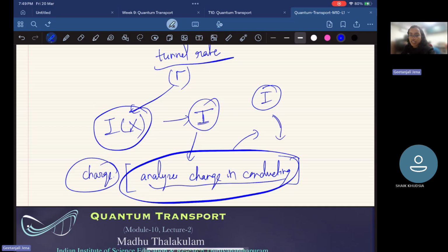So this is why we need a charge sensor: in the low current region, the tunnel rate is very low, and there is a thick source and drain barrier. Also, the device is not able to measure the current below that limit because it has a threshold. To overcome that, we need a charge sensor. There are different types of charge sensors. One example is the quantum point contact.